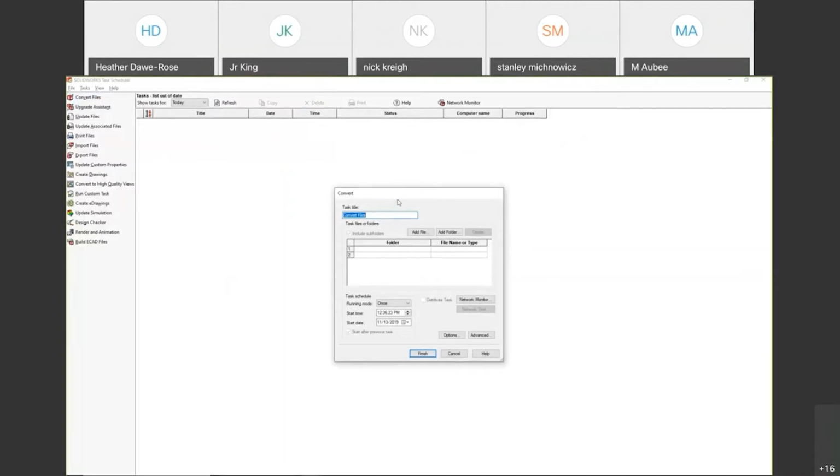I'm going to give you a little caveat here. If you're using PDM, there's a separate file converter that you're going to want to use. But if you are using just normal SOLIDWORKS without PDM integration, you can use this to upgrade your files to the newest version.